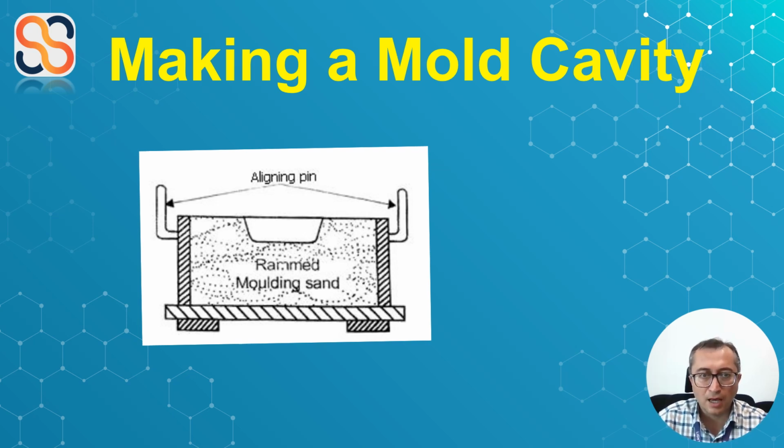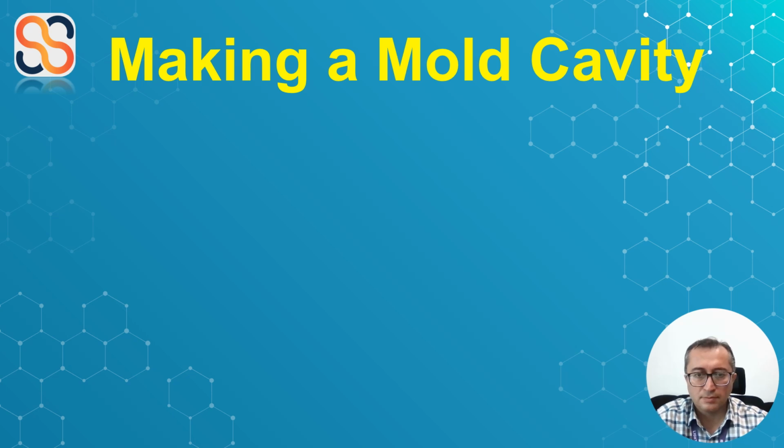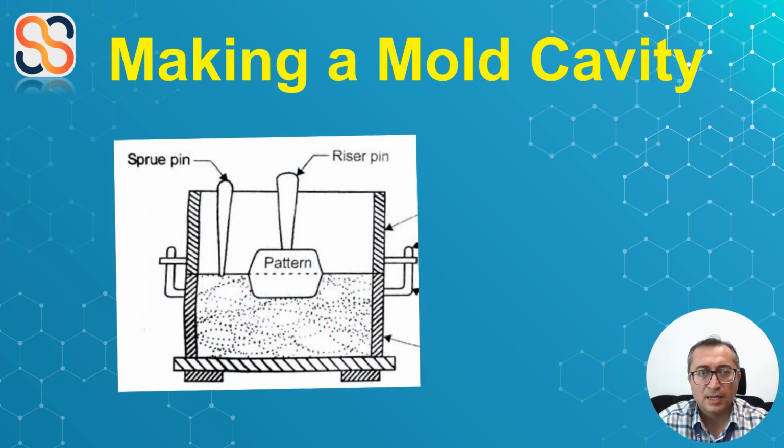Once that is done, we set the cope on top of the rammed drag and sprinkle parting sand all around the cope pattern. Now we need to insert the sprue and riser pins vertically at suitable locations. This helps us form cavities of the right size for pouring the molten metal, as you see in this image.